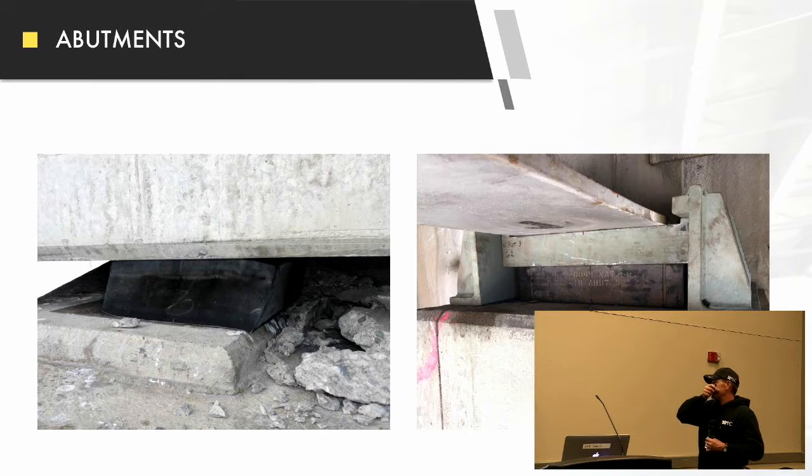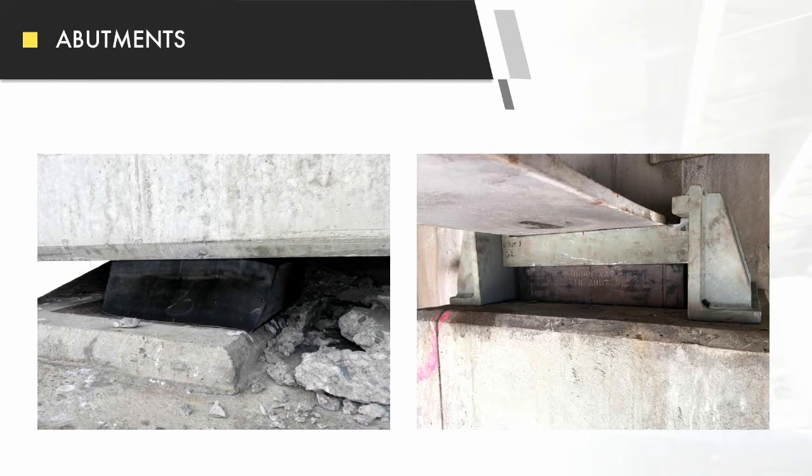Okay, here's some bearings. The one on the left, obviously, even though it's new construction, that bearing's gonna fail. Bearings need to be placed and really watched closely. This one here, you can see all the writing here on the outside. It's centered, it's squared. You got good bearing top, bottom. That's how it should be done. This one here, there's so many things wrong with it.